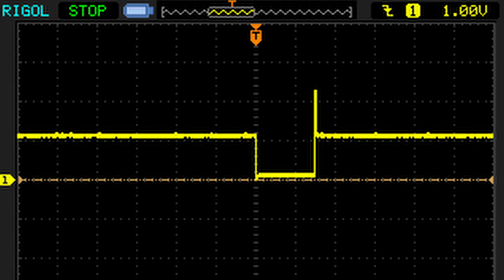So when we abruptly open the switch when the MOSFET turns off, there's nowhere for current to go. And so what's going to happen is your primary side of your transformer, that inductor will try to raise its voltage to keep pushing current through that MOSFET. And so as a result, you get a huge voltage spike.